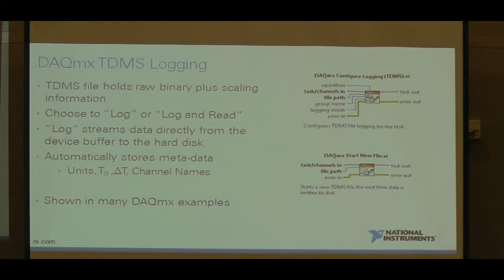The TDMS file type has some special features that when we use it with DAQmx, we actually hold the raw data from your device straight as it comes off the ADC, not scaled, not calibrated. We dump that raw data into the file, and then we dump the scaling information and the calibration information into the file. So when you choose the log option, the data is streamed directly from your device to the disk. It doesn't come into LabVIEW. DAQmx doesn't have to spend any effort scaling it. So it's tremendously efficient compared to the standard producer-consumer.